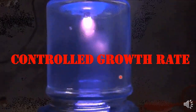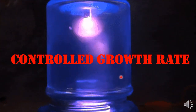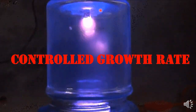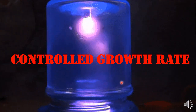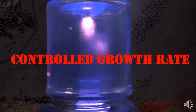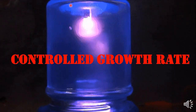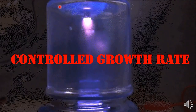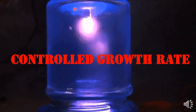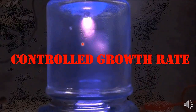Initially, if you want to deposit in a layer by layer fashion, gallium arsenide is evaporated and deposited in a layer fashion at molecular level on the substrate, and then the shutter closes the gallium arsenide. If we want another layer of gallium aluminum arsenide, the precursor chamber of gallium aluminum arsenide is heated, and the gallium aluminum arsenide is evaporated and transported onto the surface of the deposited gallium arsenide layer, and we get the gallium aluminum arsenide layer on the gallium arsenide layer. So in this way we can prepare a layer by layer